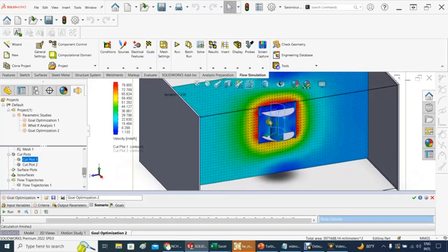That's something that I need to check and keep doing a little bit more flow simulation. But again, the first thing that I will do is increase the tunnel box length. Instead of the 4 meters that I have right now, I will increase it to about 8 meters and see what happens. Obviously, this is going to take a while doing the iterations and so forth. Well, more than enough.